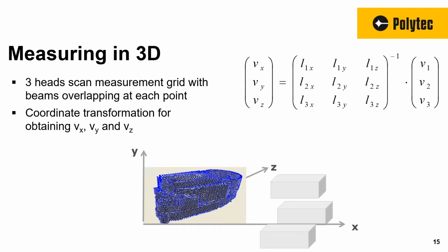In a lot of cases, the direction of motion is not known, in which case it is recommended to use a 3D vibrometer. This consists of 3 vibrometer heads or 3 scanning heads that measure the same location, but from different angles. Knowing the geometry and the orientation of the object as well as the sensors allows the system to extract the orthogonal velocity components in X, Y, and Z. This process we will also go into more detail in a later section.